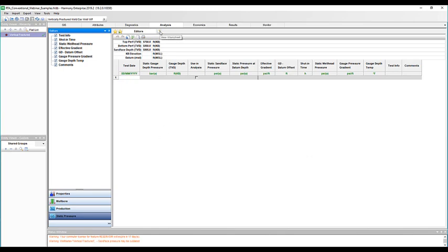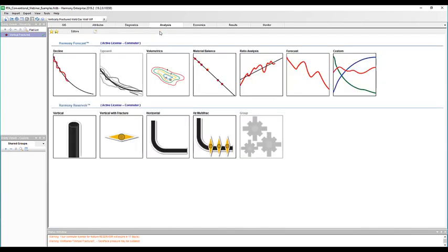Now, we've taken a look at already in the webinars the theory behind type curves and flowing material balance. So this is what we're going to start off by doing. If you remember, rate transient analysis incorporates both your rates and your flowing pressures to understand the reservoir and to create reliable forecasts. So we've already taken a look at our flowing material balance and our type curves. So let's start off with that.